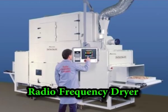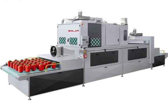Rate of heat transfer is very low in radio frequency dryers. Best part of radio frequency dryer is that the electromagnetic field self-regulates with respect to moisture present in the food material. As the drying progresses, it reduces itself with decrease in moisture content.